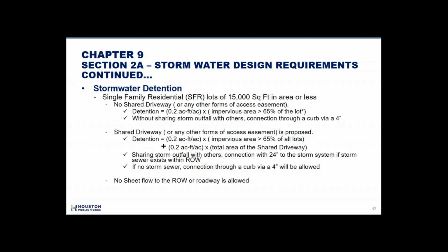And then I just want to make sure everybody understands there is no sheet flow. We constantly get developments coming in here that want to do sheet flow. And I know at one time sheet flow was allowed, sometimes even for large developments. But post Harvey, August of '17 changed all that, and you're not allowed to just sheet flow. You'll have to do some sort of subsurface system.